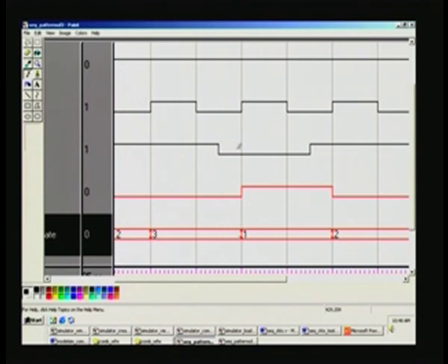So, before this you are free to make the transition either here or even here, soon after this, right. So, anywhere you can make the change. It so happened that I put it here, that is all. Whatever you make, when the clock strikes, it plainly looks at the input, and it will go as per that. So, for this state only at this following clock edge processing will take place, that is what I want to impress upon you, right.